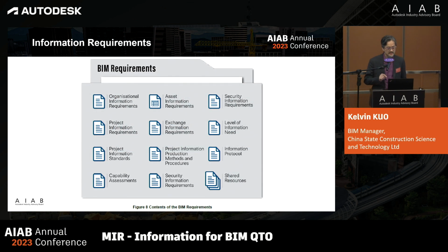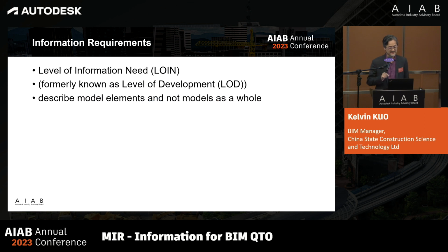Regarding those BIM requirements, a very important thing we need to know is the level of information need, which formerly we called the level of development, LOD. The LOD divides what kinds of model information or model elements we need to produce, and we need to emphasize the modelling according to the different development stages and design details.